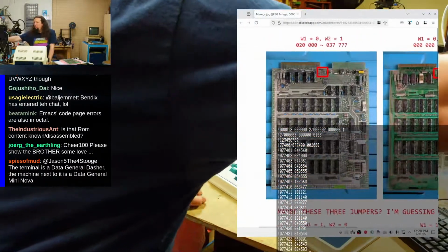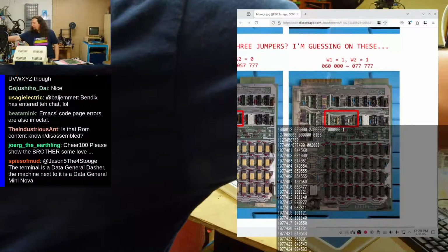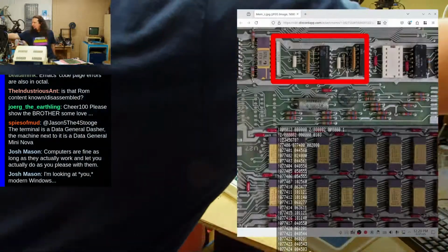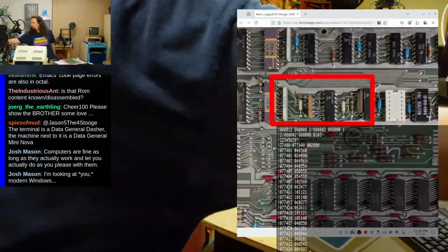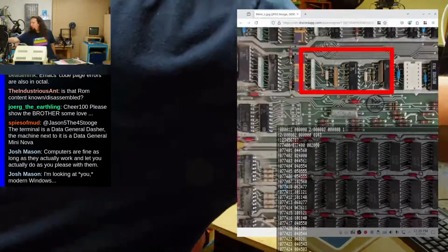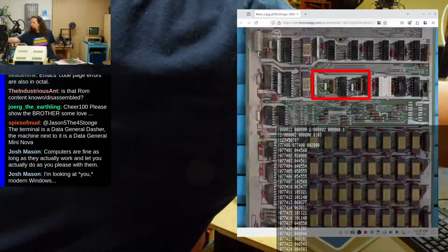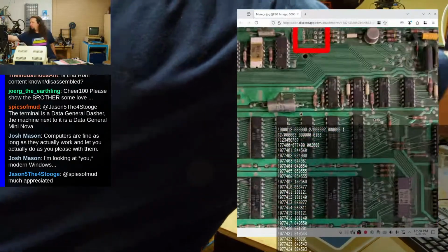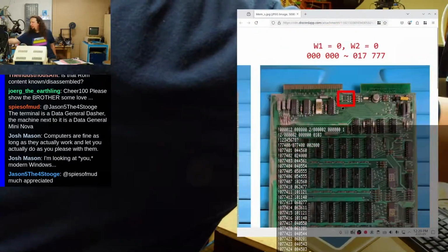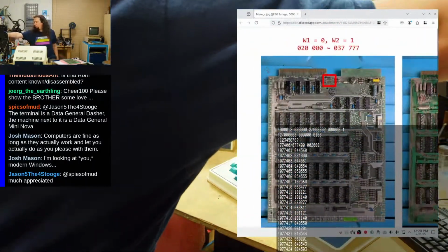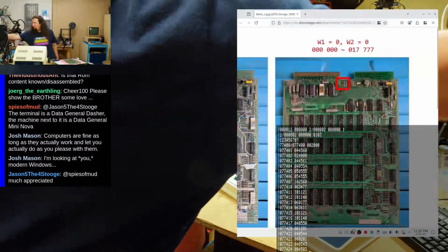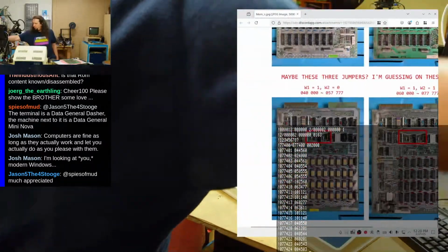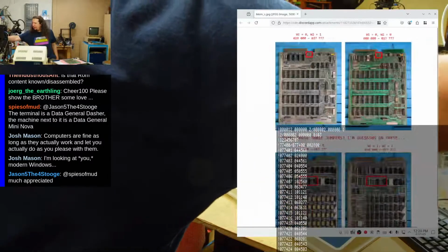I really like it. So these are my 4 memory cards. They have jumpers on them for different addresses, which is what I expected, and all 4 cards are configured differently. There are 3 jumpers here, only 2 jumpers there, 1 jumper in position 2 up here, and 1 jumper in position 3 over here. Zagi looked through the manuals and believes the address ranges should be these values for the different cards. The problem is we can't set any memory at all.